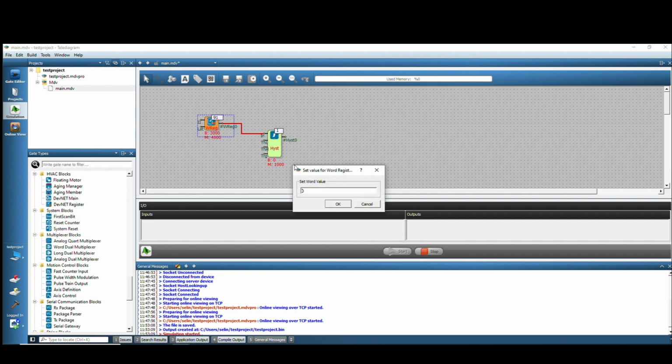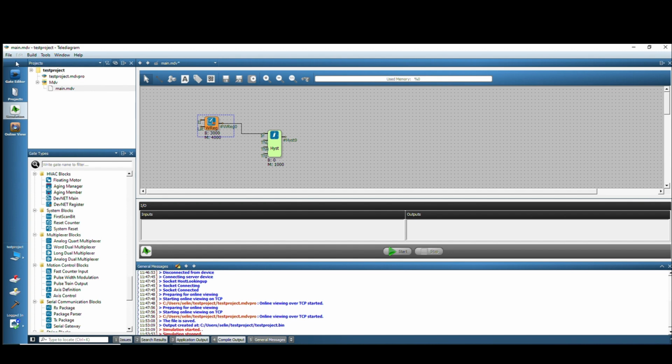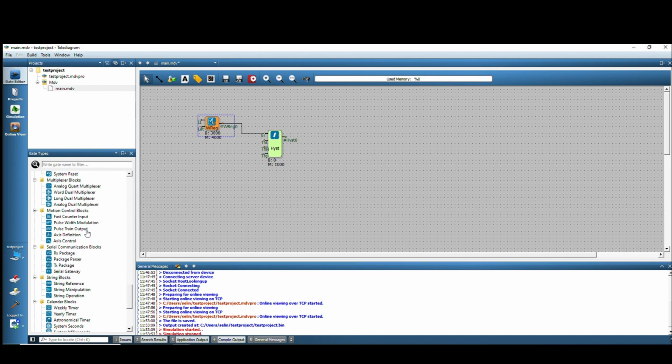We sent a value between 90 and 20, and the output is still 1 until it drops below the lower threshold. Thus, the on and off operations can be managed within the threshold range. We sent another intermediate value, still 0. It will return to 1 as soon as we exceed the upper threshold again. This is the working principle of the hysteresis block. You can also trigger the trigger input inside with trig active operate.